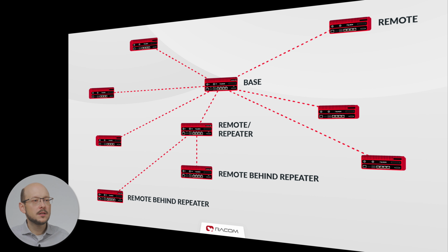There are 2 station types, base and remote. Remote can also be set as a repeater for another remote. Base is used to control the traffic and usually sits in the central node. Remotes are all other stations. The base station needs to be made aware of all remotes which will communicate by configuring them in the base-driven remote section. Make sure the radio parameters are set the same as parameters set in the remote unit.